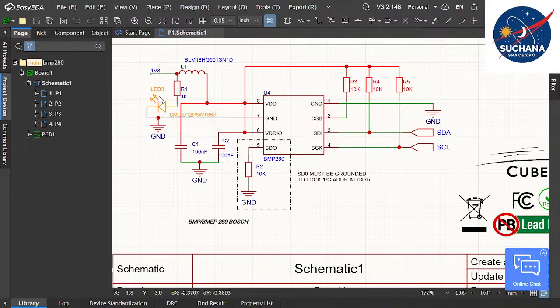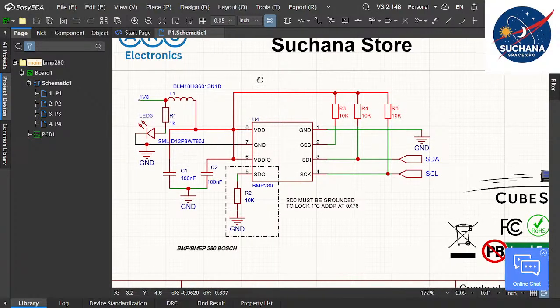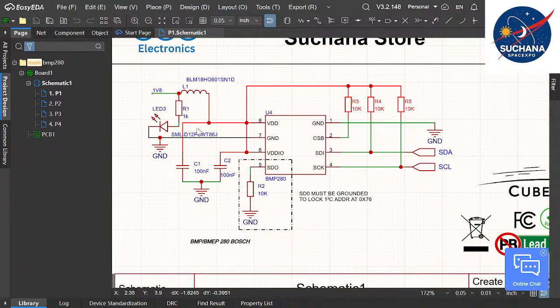If you keep a resistor just before the LED, we call it a current limiting resistor, based on the current limitation. There's another classification for data transmission rails: if one terminal is connected to a data transmission bus and the other is connected to the positive terminal, we call it a pull-up resistor, or if it is connected to ground, we call it a pull-down resistor.